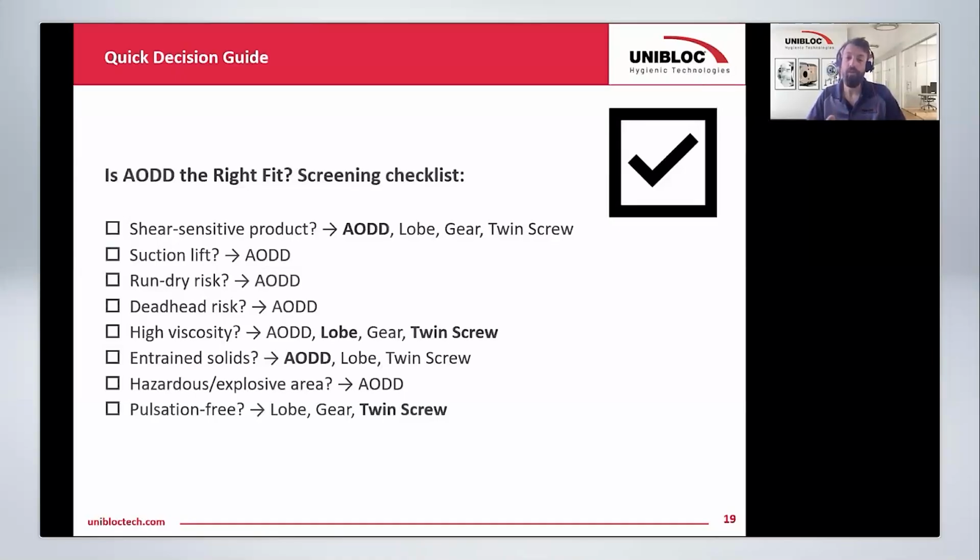You can use electric pumps in those locations, but then you have to make sure that your motors and any other electric components meet the standards of that location. So in Europe, you have to make sure it's an ATEX motor, or in the US, there's class and division motors that you have to make sure you've got the right class, the right division for that location. So the AODD is just intrinsically safe for those areas. The other pumps, you have to take a lot of considerations to make sure they're safe for those areas.